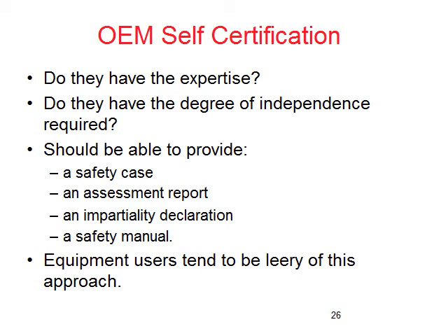I don't think that the OEM liked that feedback, because about 3 to 6 months later, they issued a self-certification to SIL 3, no redundancy, which is really not even a credible approach. So the market's a little leery of this, because often OEMs will do it without fully understanding what they're saying they can do, or frankly, as a shortcut.